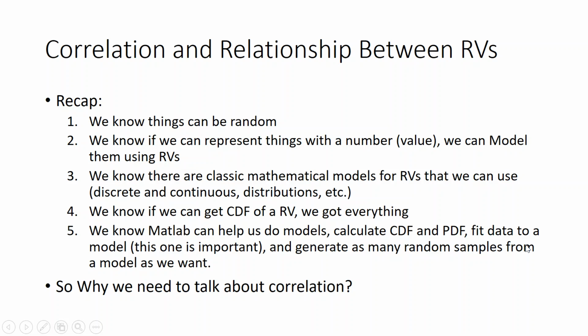that if you know how to use help in Matlab, and you also know which type of distribution you want to use, then you got some data. You can always fit the data into a known model. This one's quite important because we're probably going to use that a lot. Frankly, say you have tested some concrete, you came up with 20 tests, different strengths. Then you can fit it into a normal distribution, and then you can project what's a very high percentile, which is probably not possible to do with an empirical CDF because you don't have too many data points. But by assuming a model, you can do it.